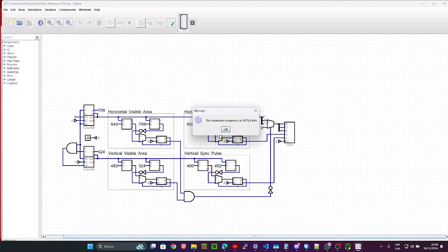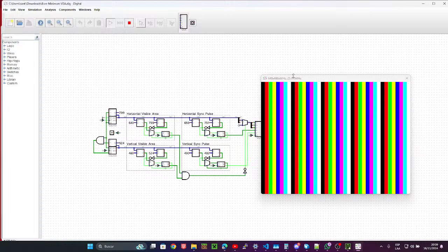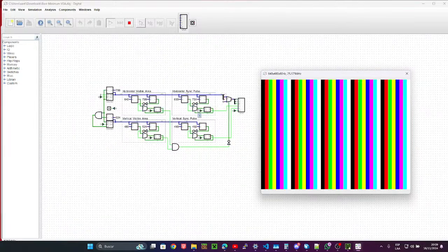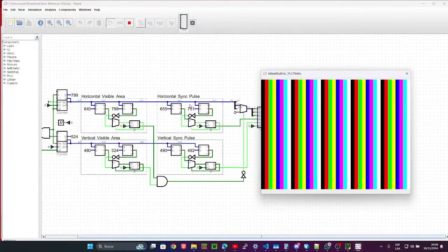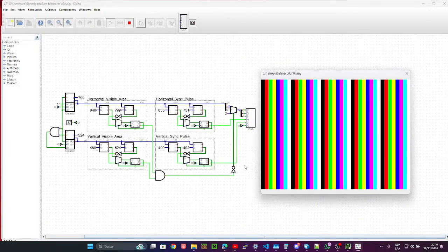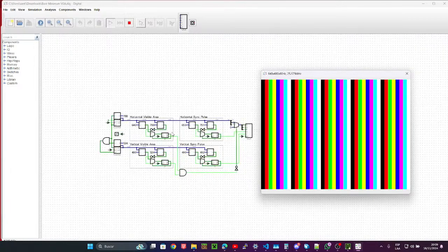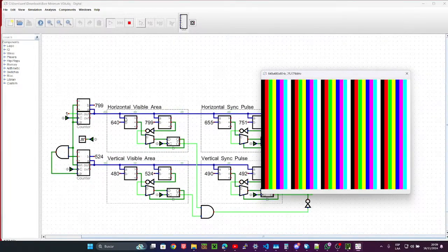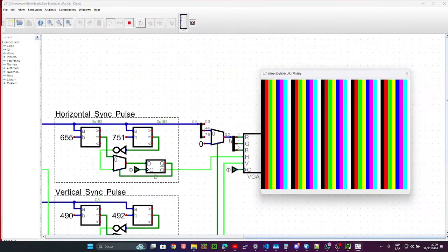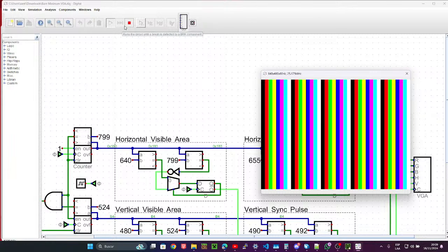That's 1.6 megahertz, and that's slow. 1.6 divided by 25.175 times 100 is 6.3% of real life speed, which is about 4 FPS.